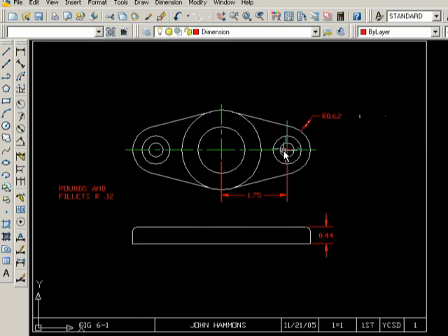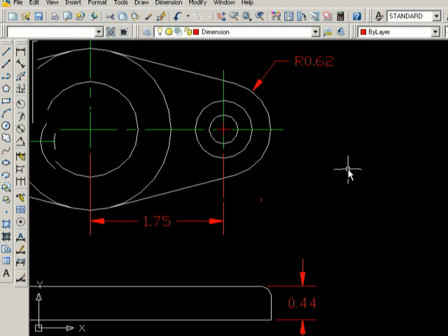You notice in the middle here, I've got red center lines. The center point of this radius is going to be selected. All right, so I'm going to zoom in, and I have to delete these. These are bad. We want the green center lines here. So every time you use this, you're going to have to explode this dimension tool and erase these lines.